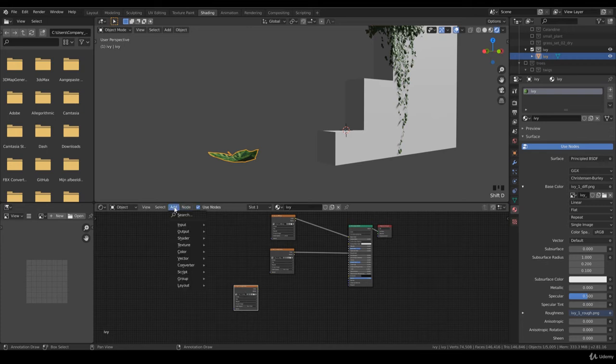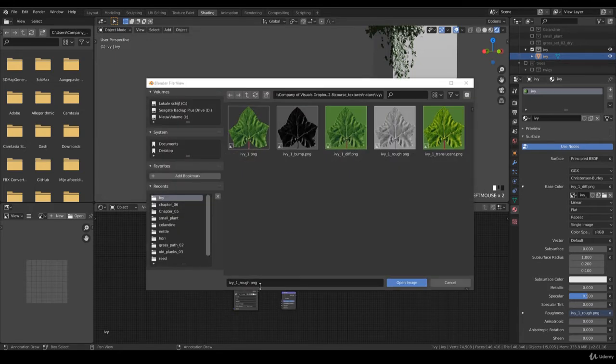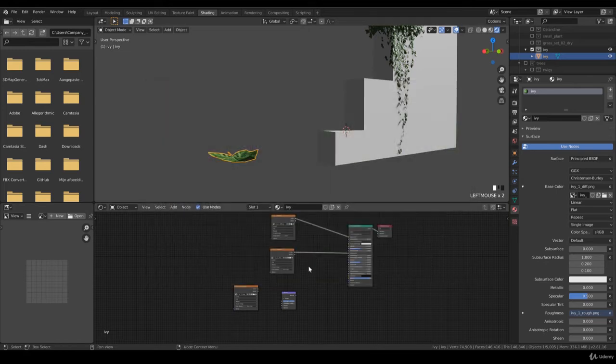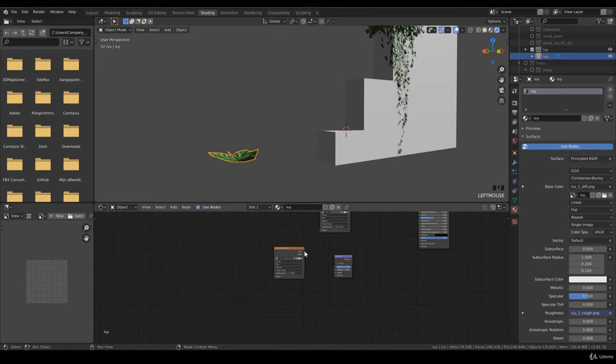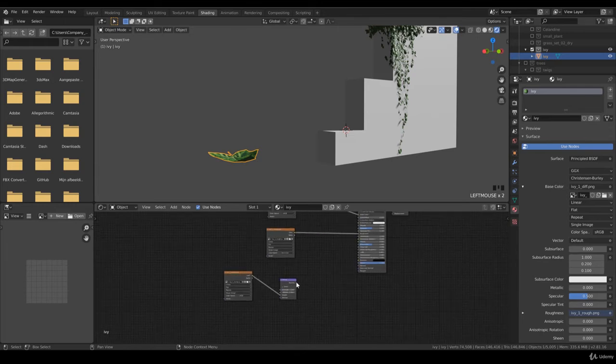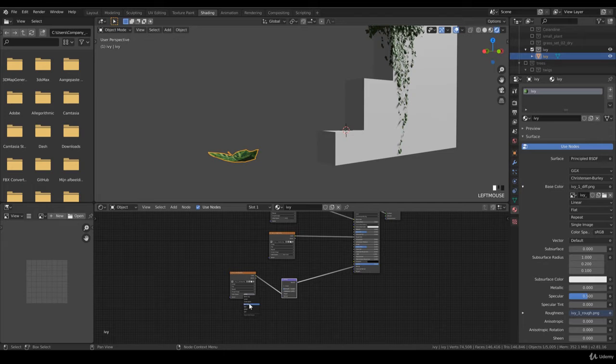It's no problem to do this again. Color, vector, bump, and you want, oops, focus on it. This is the roughness. You want to have the bump texture. Bring this in with a strength of 0.1. I put this normal in the normal, and with sRGB to non-color data.